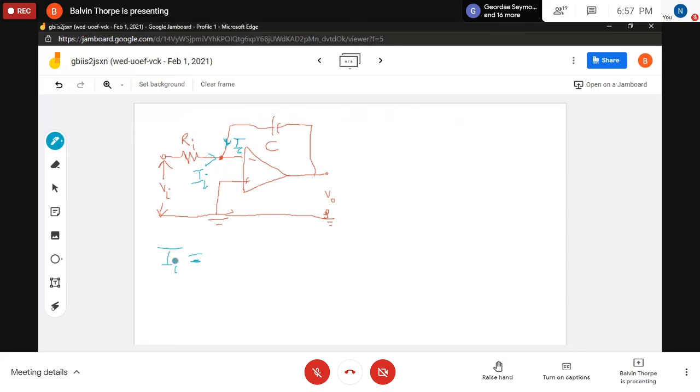All right, so II, from what we know, II equals what? In terms of, it equals minus, in this case, IC, because IC is the feedback current, right? Because of virtual ground. And by now, everybody's supposed to know that. No question asked. But we can express these currents in terms of voltages, right? So we can say II would be VI over